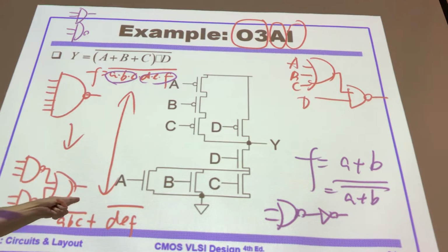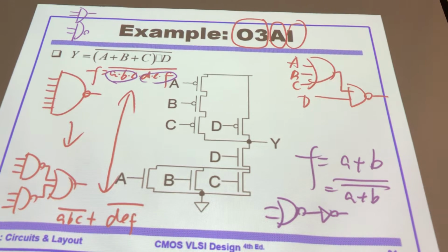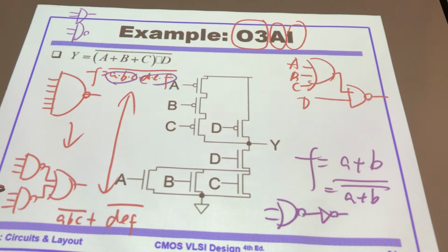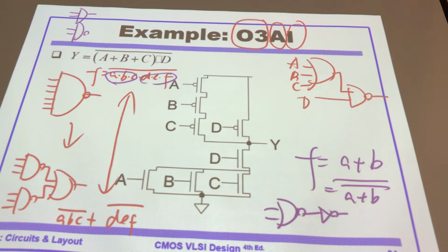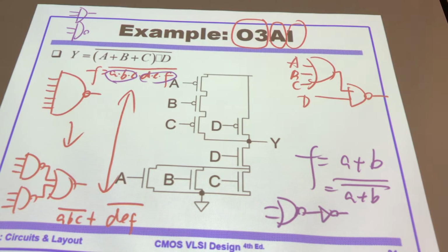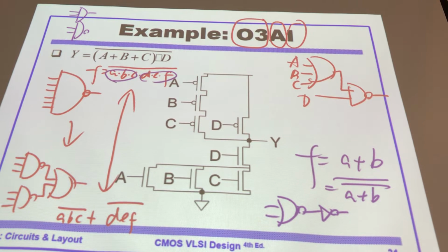That's going to be your critical path, meaning your longest delay. That determines your circuit speed. When we talk about circuit speed, we also mention worst case, not best case. So that determines your circuit delay. Good question. It should be 3, not 4 and 2, because then it's going to be slower. Any other question?